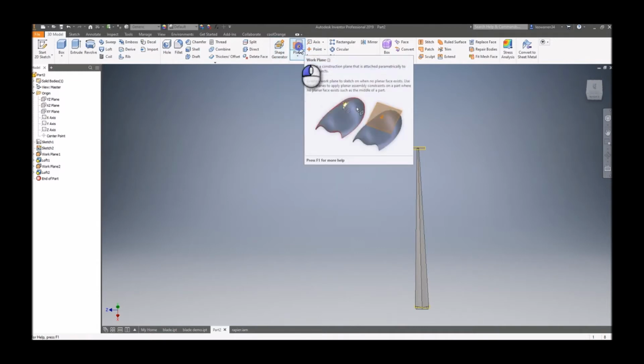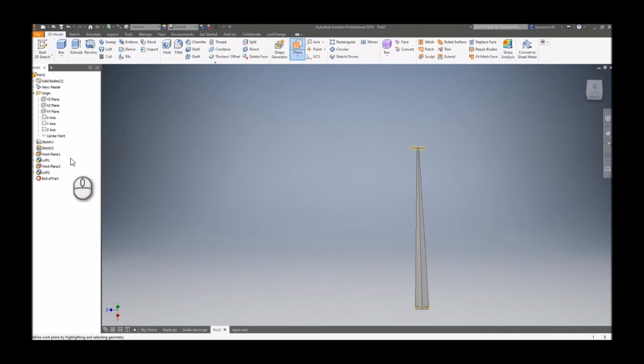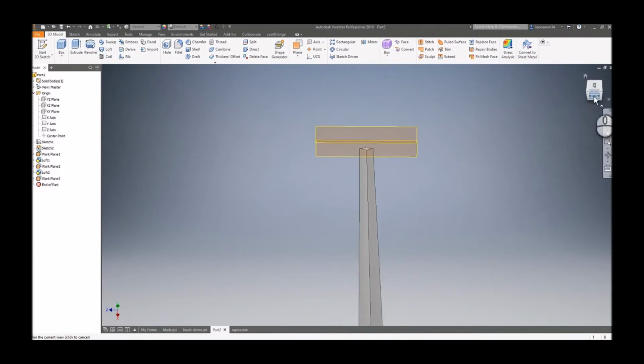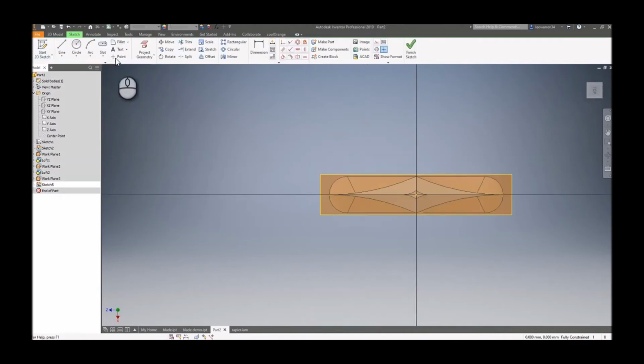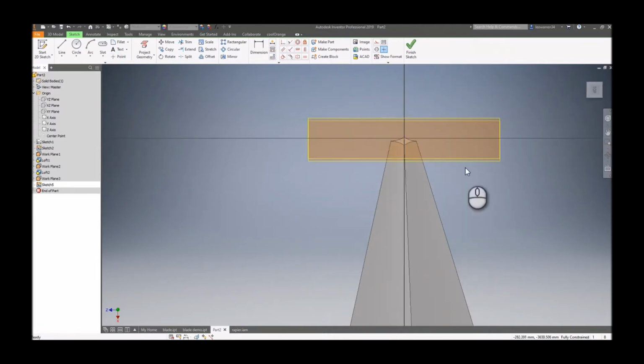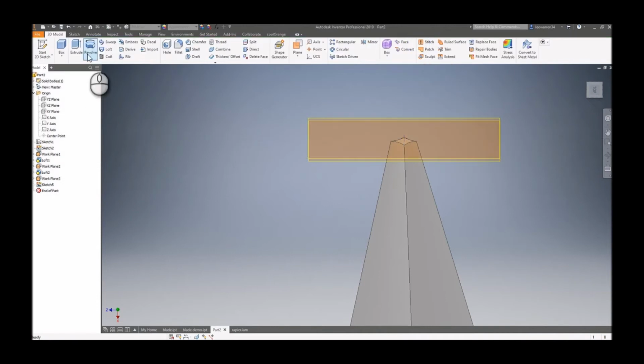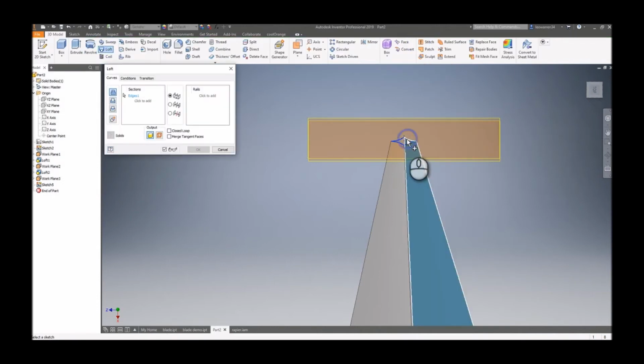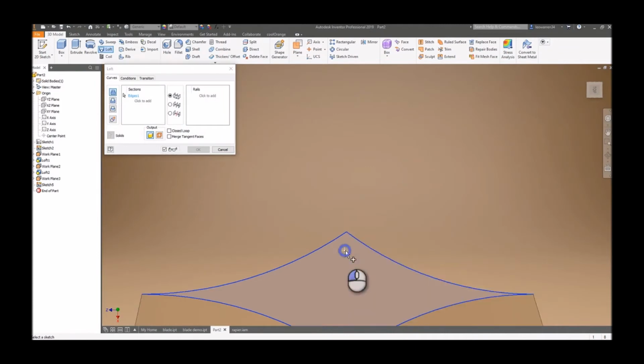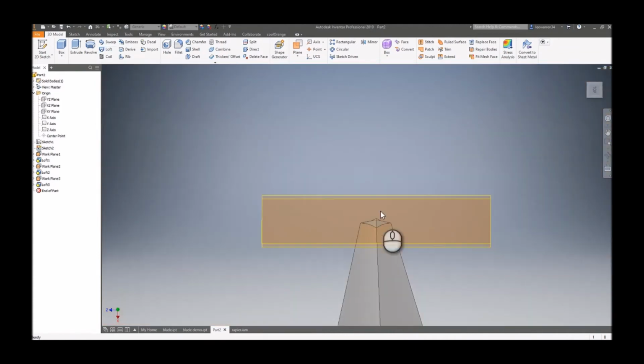Next job is to actually put the point on it. So that's just going to be another XZ plane. By the way, all the way up I'm going to say 5 at 5. So you've got a plane on top of the plane, and it's going to start a 2D sketch on top of this plane. Center point. All you've got to do is drop a point down, click OK. And all that then does is click Finish, Loft, select the point, click OK.